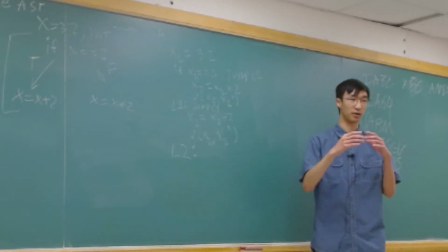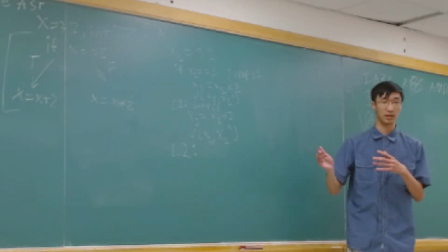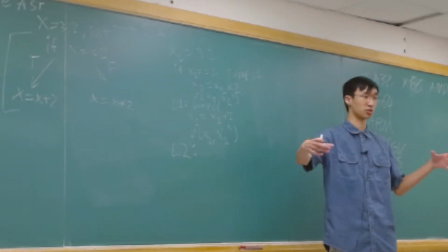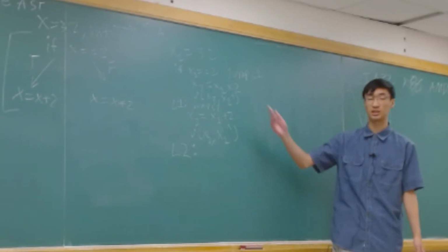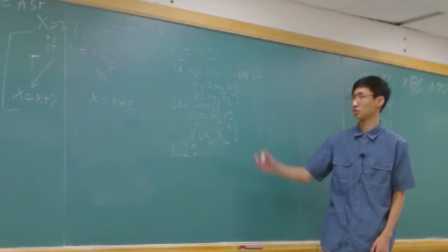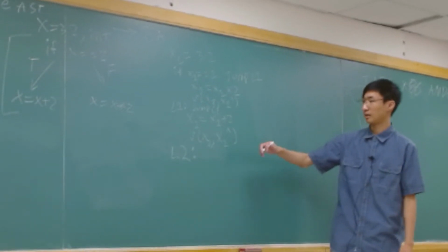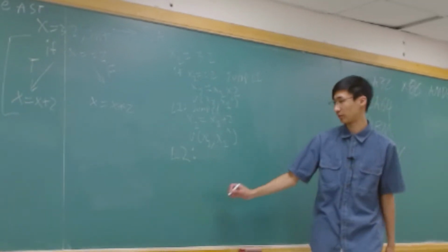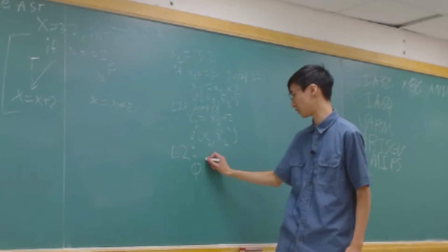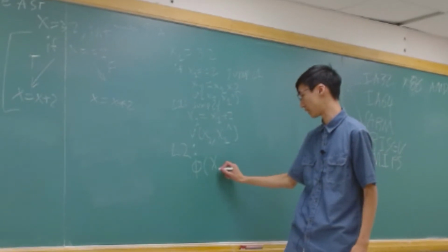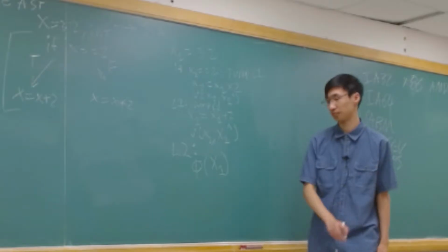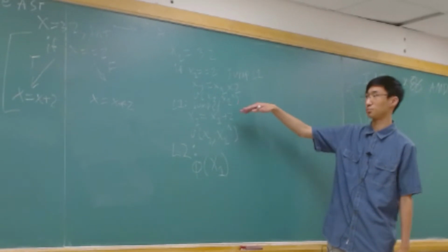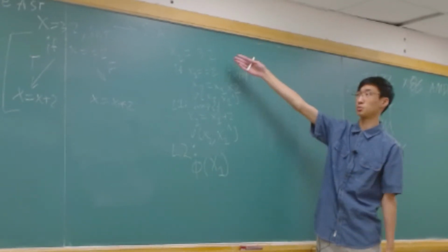Because the shift left is actually a faster operation than a multiply. Multiply typically takes a lot longer because you have to have a larger circuitry to actually be able to multiply. But in this case, we just know we're going to move our data 1 over. So we'll do that. And then it turns out that you don't actually need this merge anymore, so it's fine. And then I missed one thing, which is you need to state that you're merging x1 so that you can say these two branches are the same, but this merge would disappear and this merge would disappear because all of that would be useless because we know what 32 is.